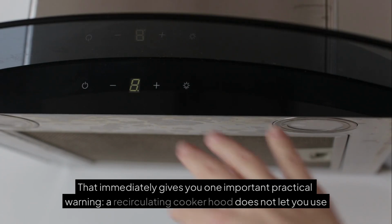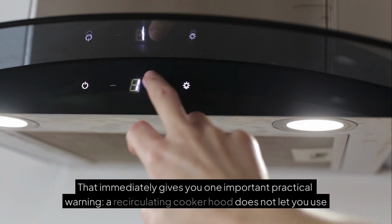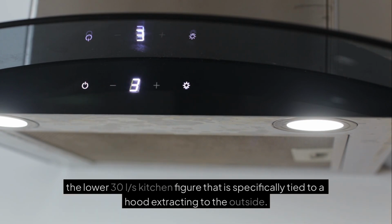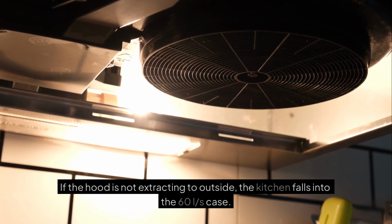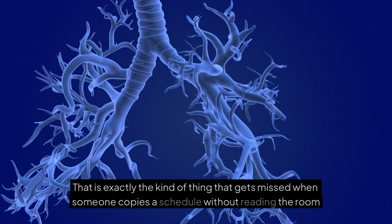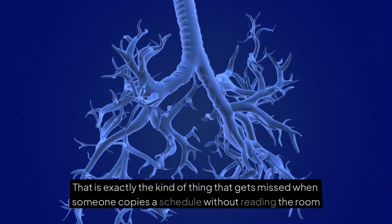That immediately gives you one important practical warning. A recirculating cooker hood does not let you use the lower 30 liters per second kitchen figure that is specifically tied to a hood extracting to the outside. If the hood is not extracting to outside, the kitchen falls into the 60 liters per second case. That is exactly the kind of thing that gets missed when someone copies a schedule without reading the room definition properly.